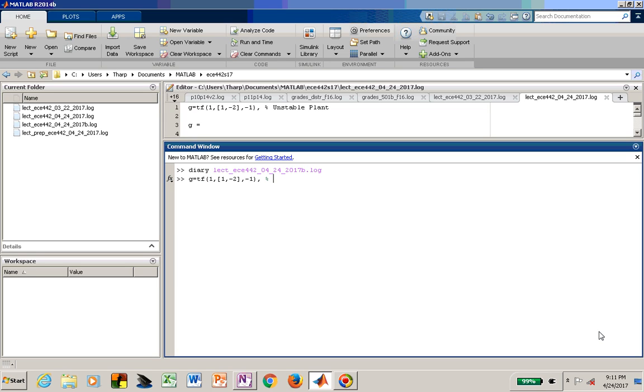So here is our unstable system in this example. Matlab will know that it's a discrete time system because we gave it that third argument in the function, a value of -1, which says we're not specifying the sample time, but we still have a pole at z equal to 2.